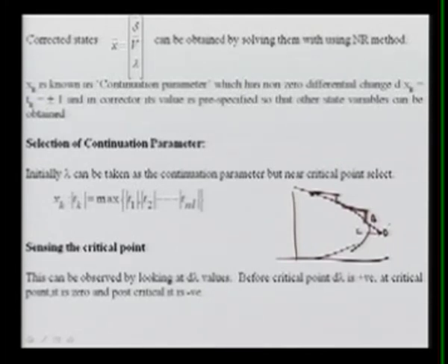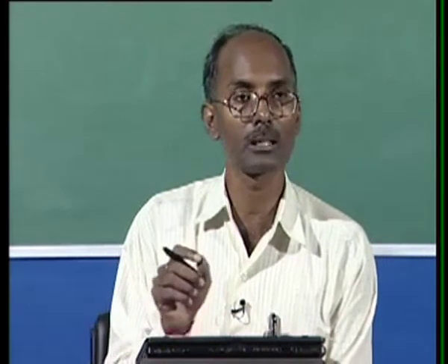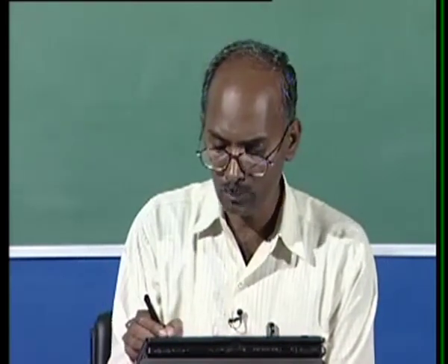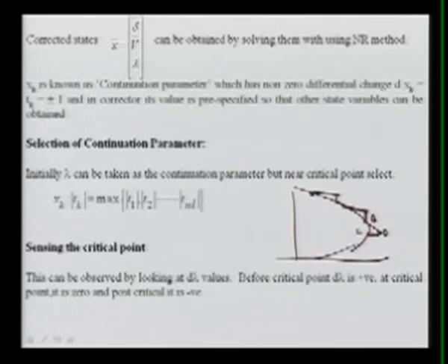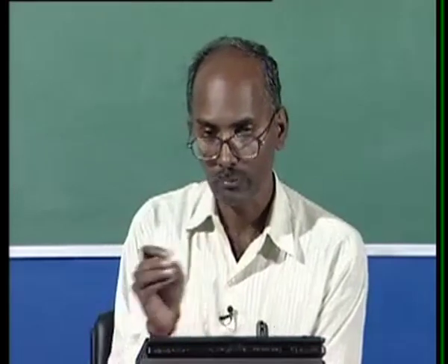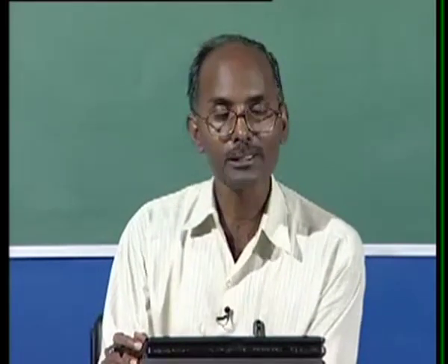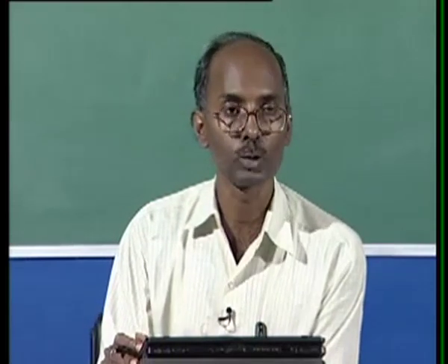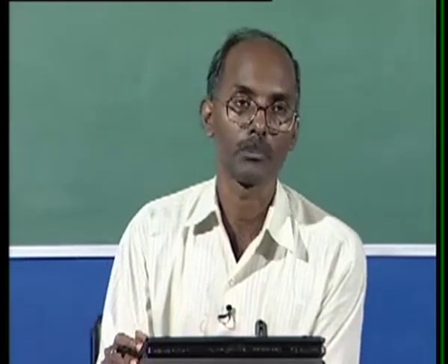So in this case, we normally fix the voltage, meaning we never estimate the load there. We fix the voltage and then correct, and then we can reach this point E. So in this corrector step, normally the step is chosen in such a way that we do not go beyond, and then we can get the solution. This method is no doubt very slow and time consuming compared to the conventional power flow method.